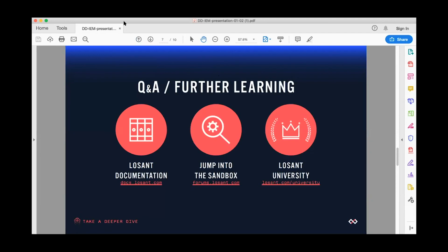Yocto is a Linux distribution. It's meant specifically for lightweight embedded machines. Think of it like an Ubuntu or Debian, but much lighter weight. So it's just another Linux distribution. It's common on small little Linux embedded machines that are for gateways. You basically have to create a recipe, create an image, and then you can write that image to the Linux machine.